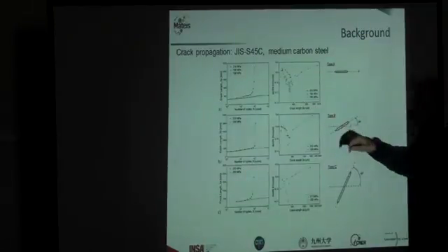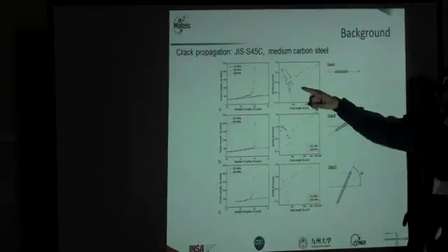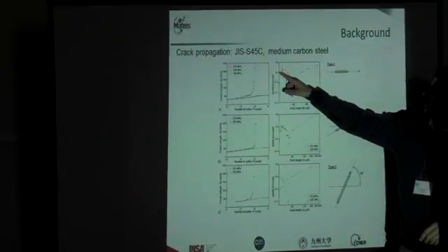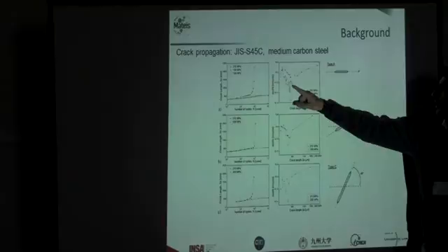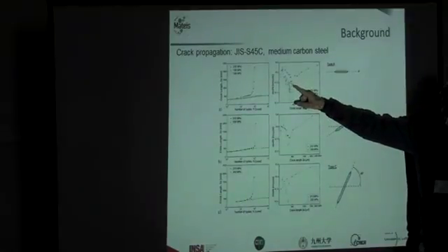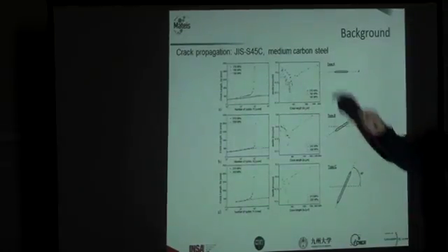And we also observed, in the fatigue tests that were done above the fatigue limit, this deceleration of the cracks that reached a minimum and then started growing again.